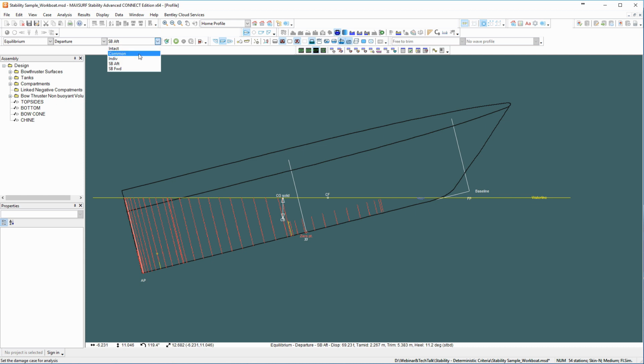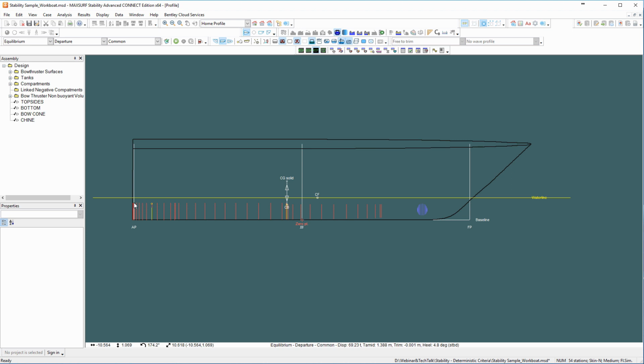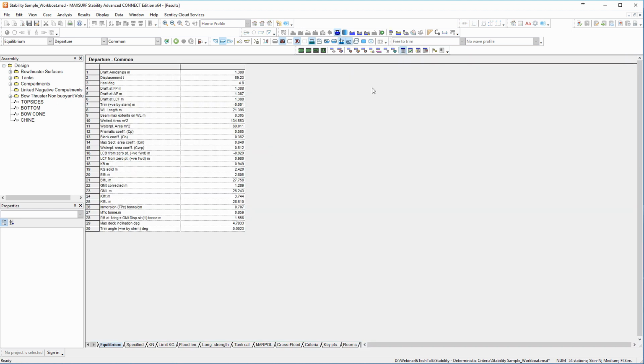So this time, let's go and have a look at when we fill to a common waterline. We've specified 10%. So 10% flooded isn't particularly far away from that intact case. Now you can see there is one consistent parallel line that covers all of these tanks. If we go back and look in that room definition,